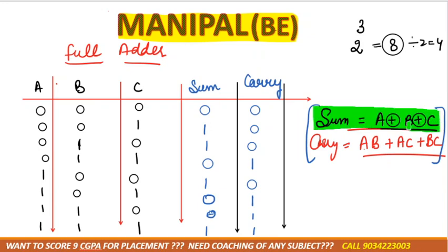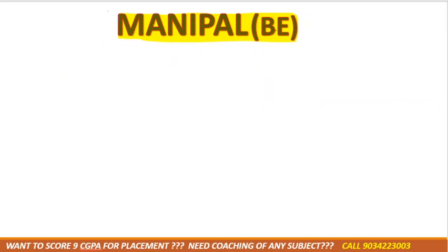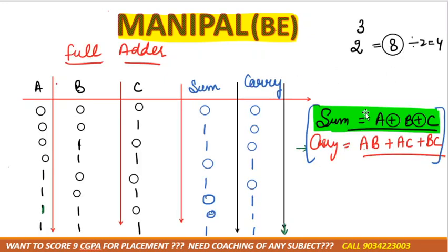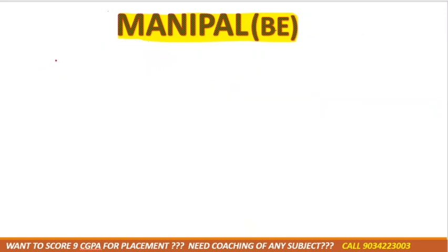Once I tell you the K-map, I'll repeat this part, that is how we can get the expression of the full adder by using K-map. We can't get the expression directly. So now realize this expression by using logic gates. Do it. Expression for sum and carry is this one. Next we need to draw and realize it by using gates.